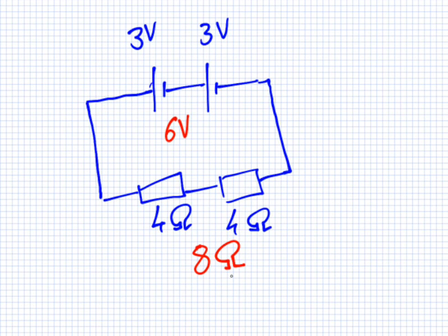Right, so now let's talk about parallel. In parallel, current is different and additive. So let me explain that. If you have current here, we'll call this I1, and this one here is I2, and they come together, then it'll just be I1 plus I2. Usually I1 and I2 are different. So current is different and additive. That's what that means.